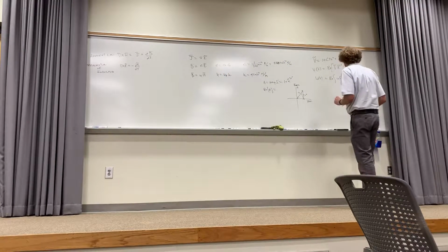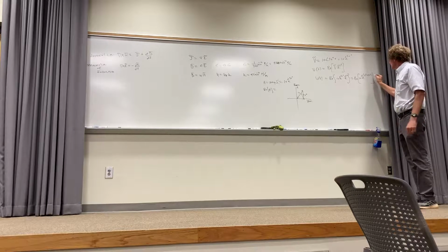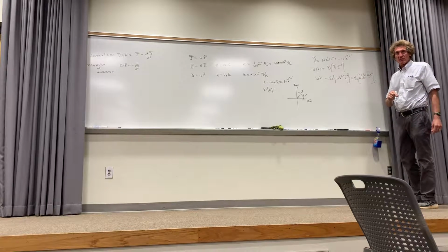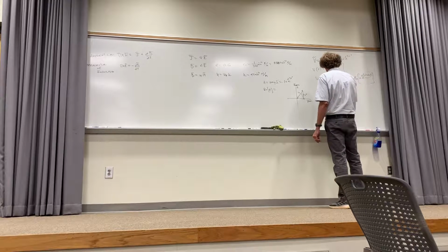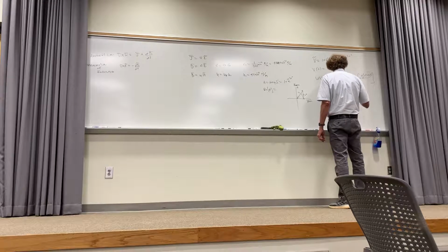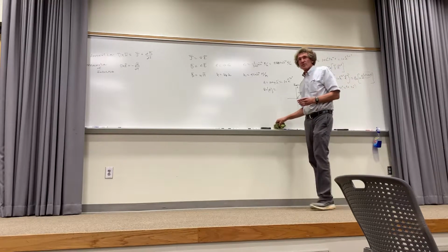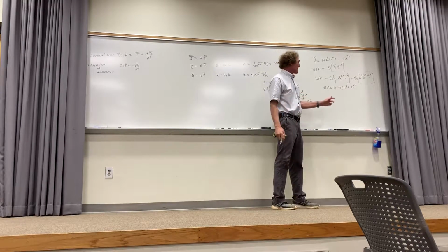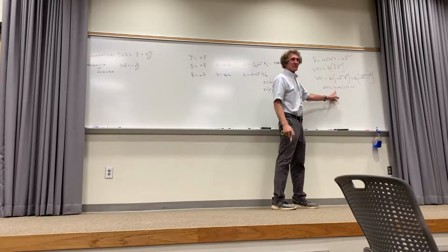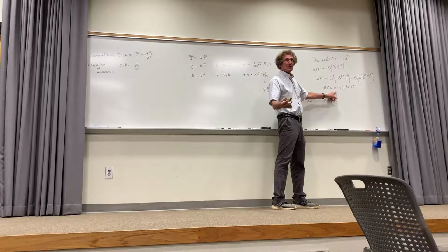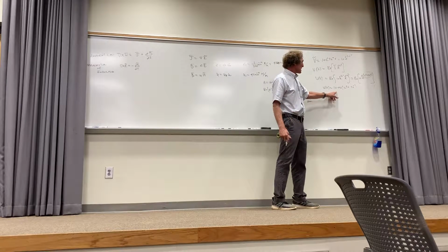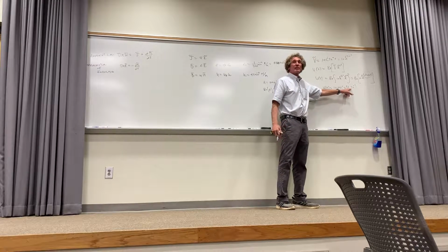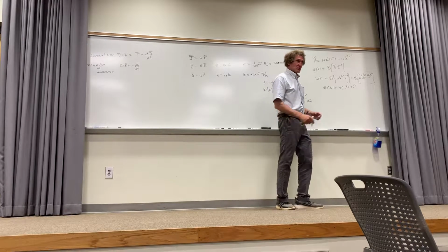I'm like that too. So when I take the real part of this, I take the cosine of this angle times 10. Follow me? So that means v(t) here would be equal to 10 times the cosine of omega t plus 30 degrees. That's sort of a review of going from phasor to time. And by the way, if we wanted to go from time to phasor, this is the easy one. They're both easy. You take the magnitude, it has to be in a cosine format, like cosine omega t plus a phase angle. You always take the magnitude, and you put it at the angle next to omega t. Follow me? That's the way you always do this stuff.